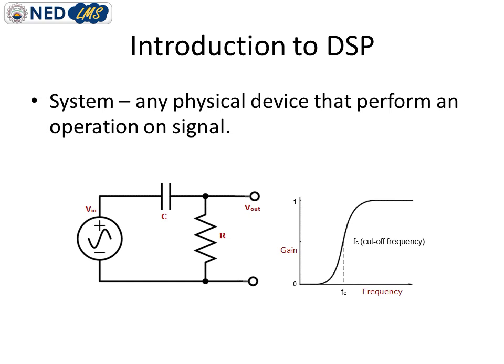So this specific arrangement of circuit elements performs some specific task, and what this circuit is performing right now is basically a high pass circuit. What is a high pass circuit? A high pass circuit, in easier terms, is the circuit which allows higher frequencies to pass through and attenuates the lower frequencies. As you can see in this figure, we have frequency on the x-axis and gain on the y-axis.